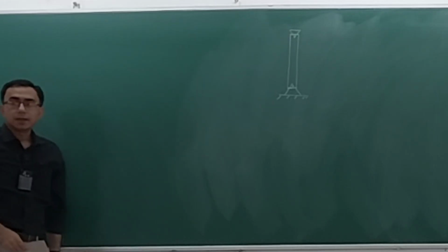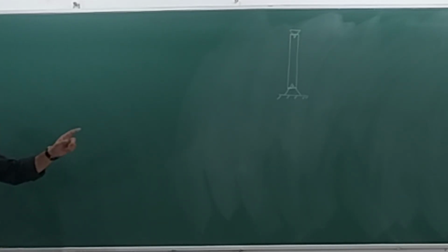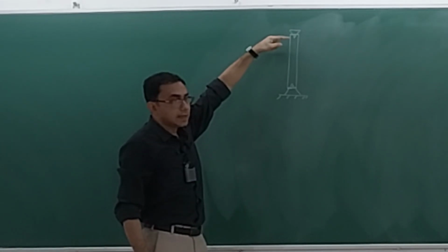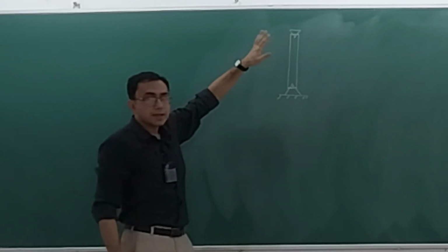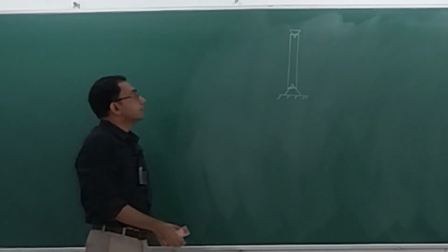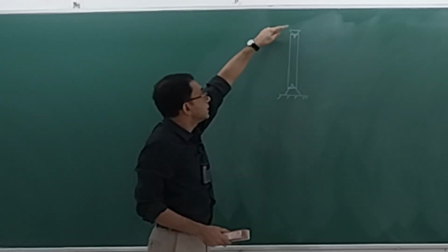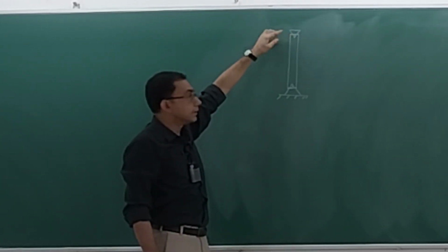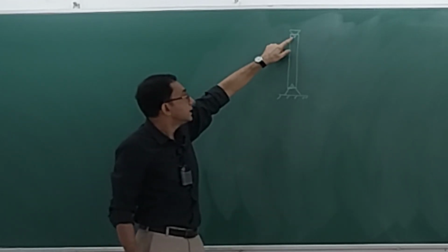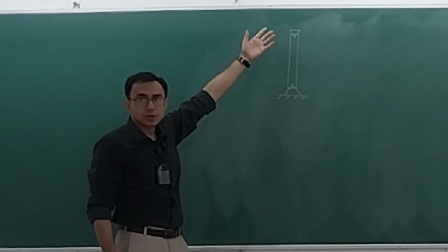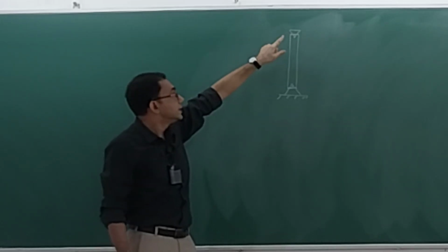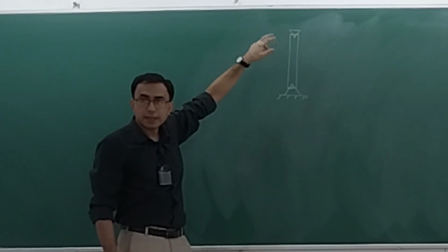Now I want the situation to be set up in such a fashion that when I apply a load in the vertical direction, this thing remains straight in the general sense. What I mean by that is that the way that I have put it here, if I now put a force here, what will happen? The hinge is not connected to anything, it is just floating. So if you put a force, it will go this way and this way. I don't want that to happen. I want this end to be guided in the vertical direction.